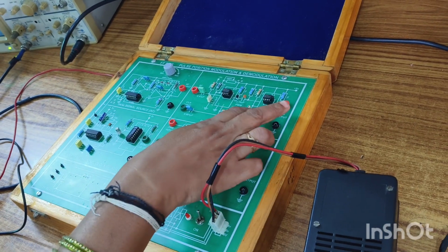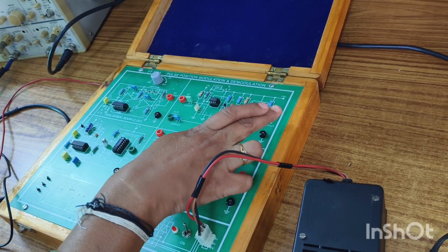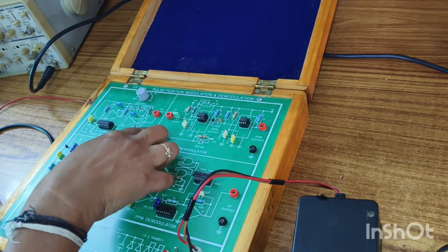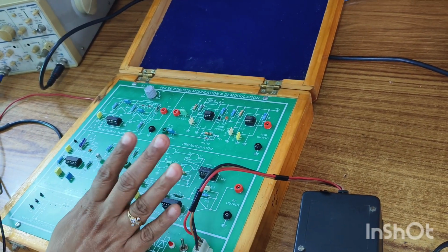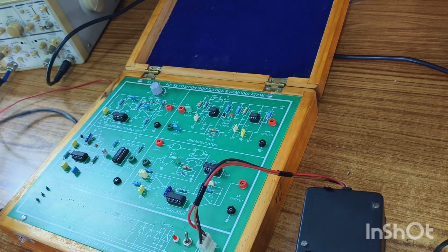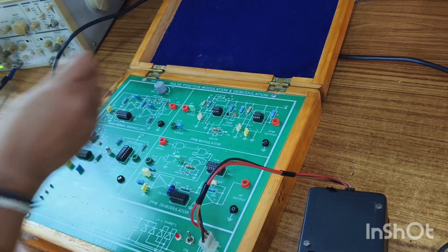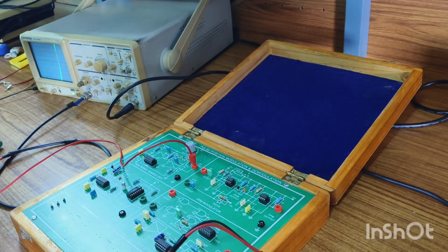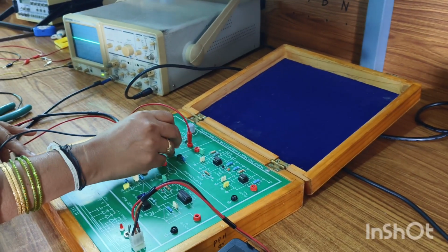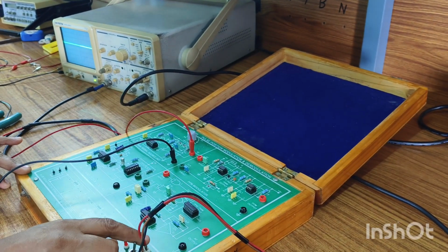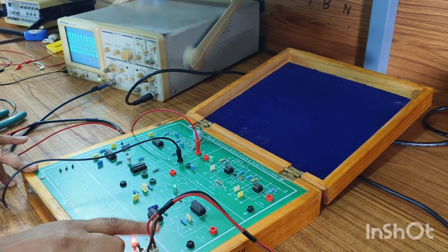Next, after getting the modulator output, give this output as input here and the clock as another input here, then observe the AF output. Now we will check one by one. Here we have channel 1. For this type of kit we need to give an 8 volt adapter. Previously it was an 18 volt adapter. That change you need to notice. Now I am going to switch on the kit.